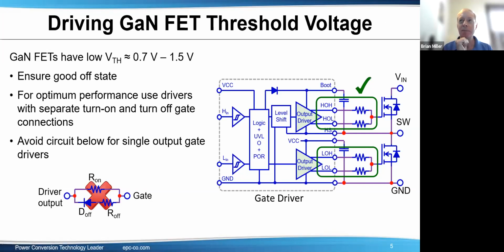With some of the early GaN FETs, over 5 or 6 years ago, if the Miller ratio wasn't as good in shape as it is now, you really wanted a small resistor to turn it off well and keep it off so there wasn't any bouncing. But I think now it's more optimization, just a matter of how much you want to go into it.